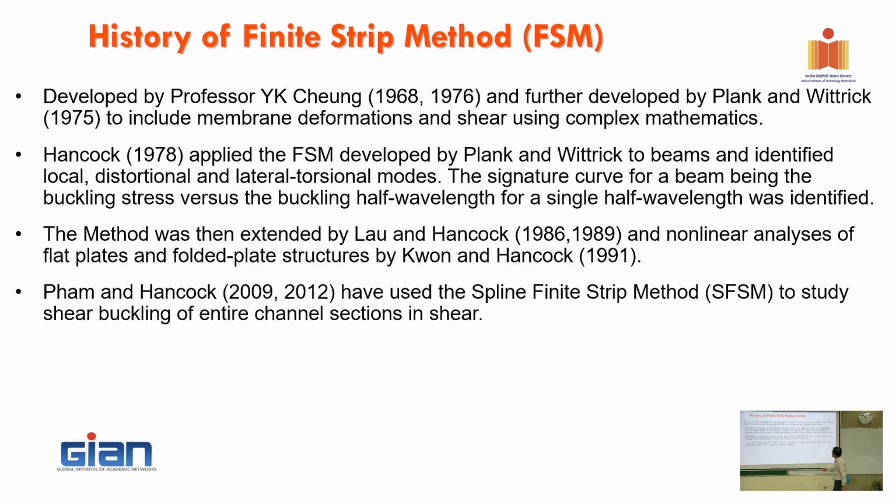And then I'm jumping to play with shear. So I'm using the same approach to dig into that, but using a different type of finite strip. What I did in 2009-12, I started to look at the shear problem, but using the spline finite strip method. Professor Hancock used semi-analytical finite strip, the psi function. But later on, when I jumped in, I looked at different ways to do it. I'm using the spline function just to use for the finite strip method.